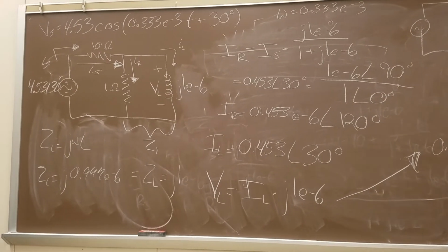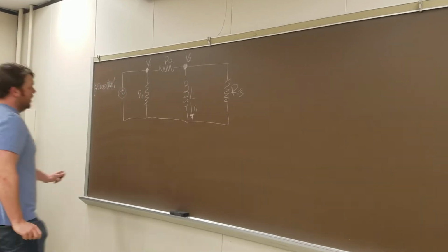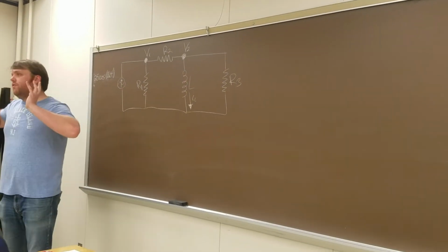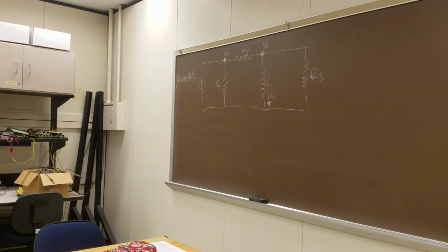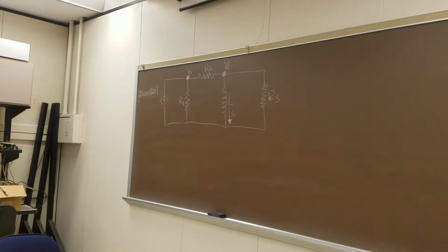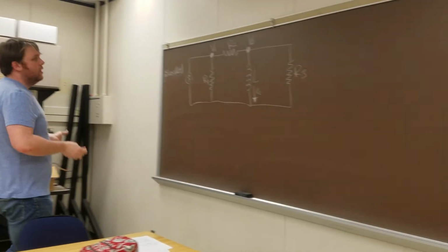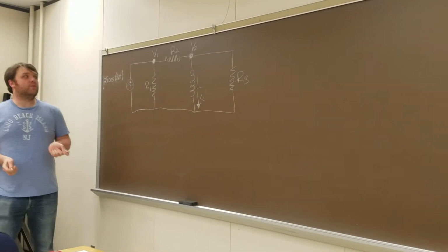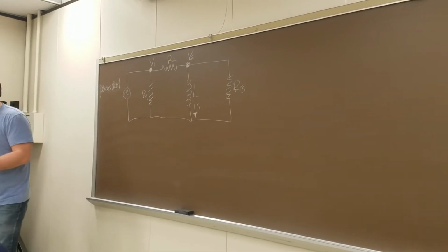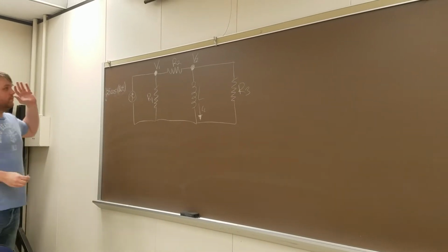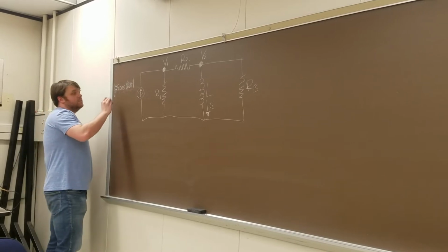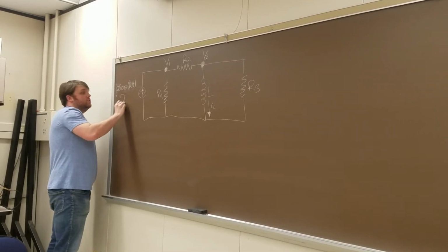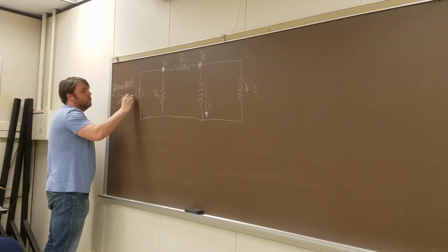We'll hold questions for a minute. Let's go look at number 11 over here. Just because solving it practically with numbers becomes kind of trivial with the numbers that show up, and I want to show the identity that appears. Okay, so the way I'm going to go about solving this problem is by doing KCL. Okay? First, again, I'm going to do the exact same thing. I'm going to convert this into a phasor. So this has no phase shift, so this is just 25 angle 0 degrees.